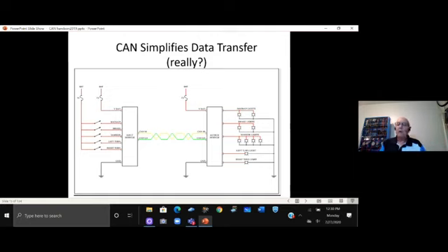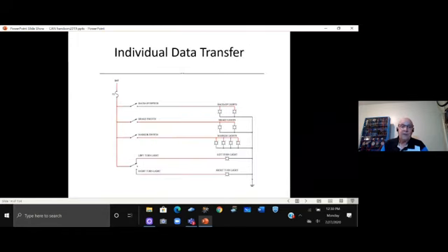There were buttons galore. You name it, and you could do it on the door. Well, that vehicle was on individual data transfer, which meant every time you closed an individual switch, you had a wire. So we brought B+ into the door, and we brought it out of the door for everything that this vehicle was supposed to do. The bundle of wires was easily an inch in diameter.